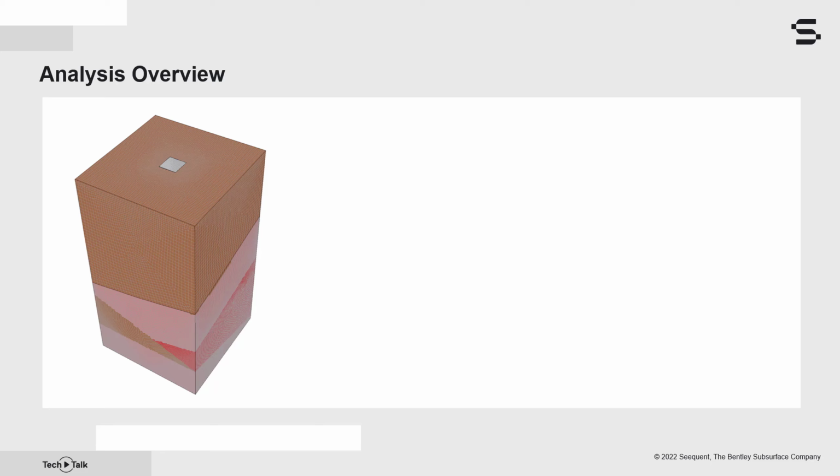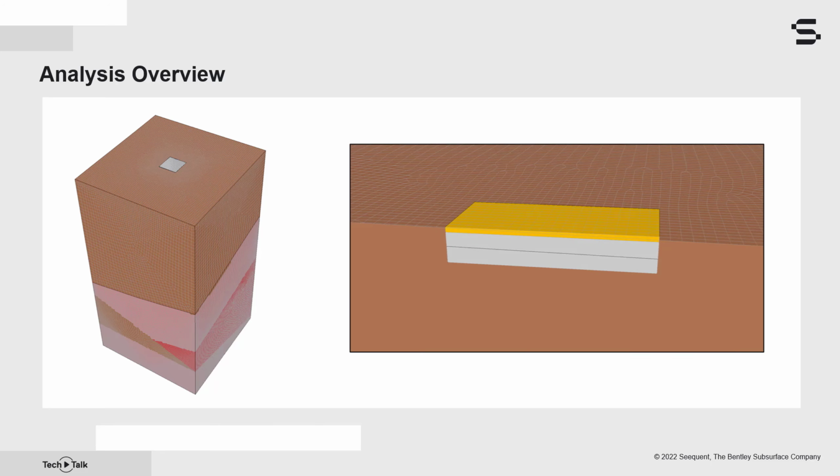In last month's Tech Talk, we created the 3D geometry associated with this project, including the building foundation, consisting of 0.25 meters of extruded polystyrene foam insulation and 1.5 meters of non-frost susceptible gravel. 3 cylinders representing the thermosyphon evaporators were added to the gravel portion of the foundation with a spacing of 3.33 meters on center. One of these is visible on this cross-section.